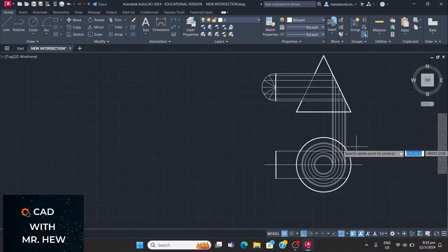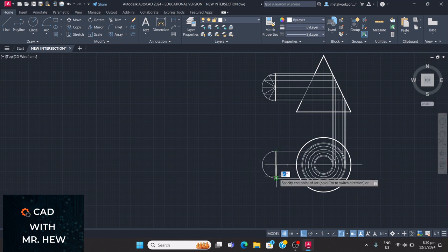All right, good, right? So the procedure that we did a while ago is to just cut up between the largest circle, sorry, the smallest circle and the largest circle down here. We cut it up into discs in the plan, and that will help us to plot the line of intersection. All right. So we are going to draw the semicircle down here too, right? So we're going to go again. Arc, center, start, end. Enter, right?